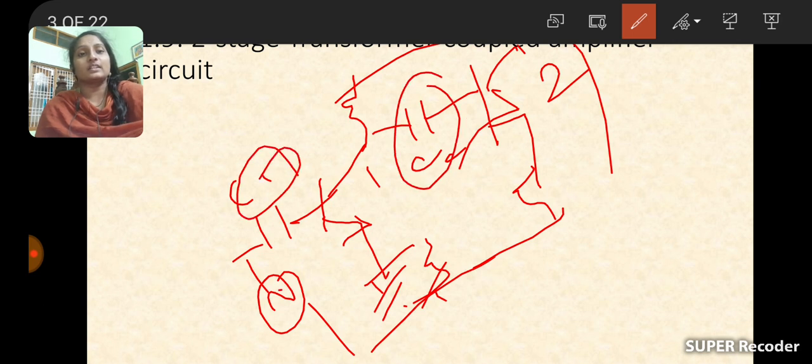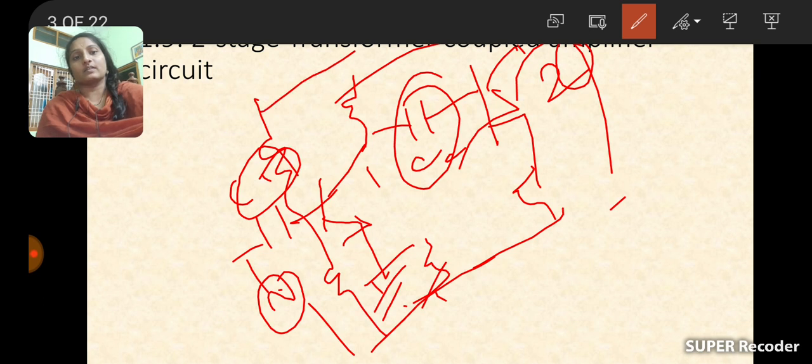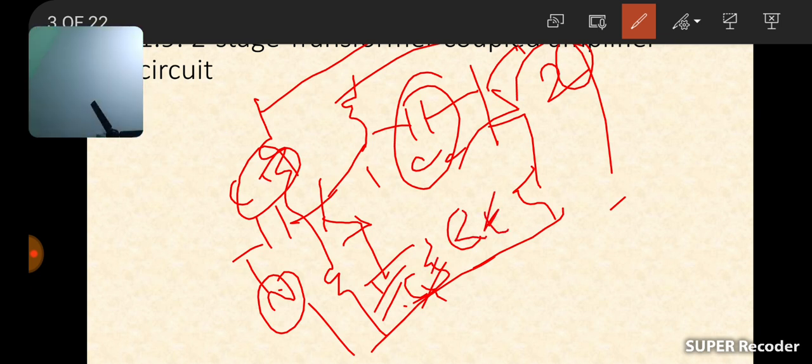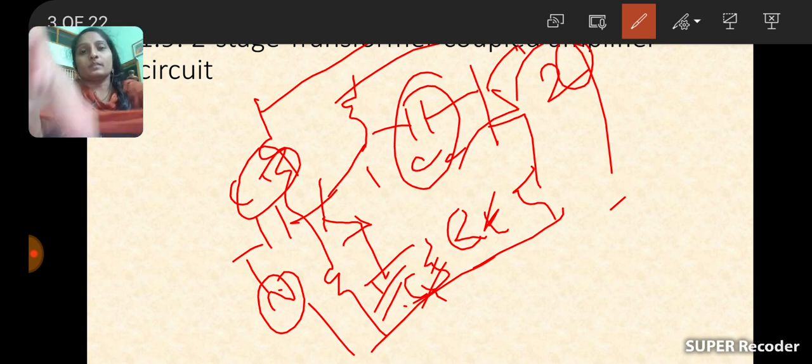C in is there, CC is there, C out is there. Okay, and both circuits have the stabilization network R1, R2, and also the emitter bypass capacitor CE and resistor RE. So each and every single stage has stabilization network R1 and R2, and the RE CE bypassing capacitor and resistor are also there.